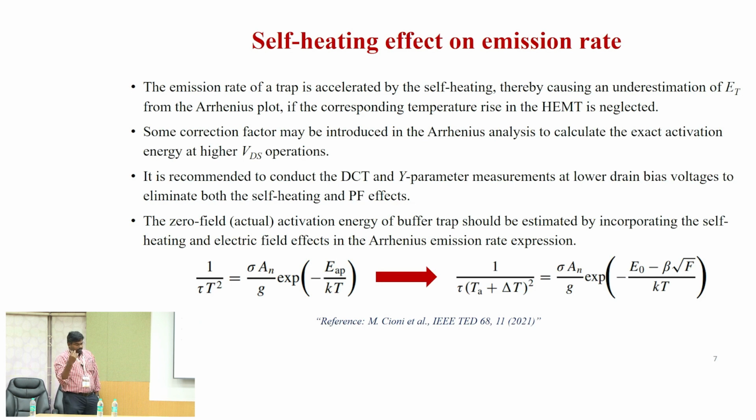Then the self-heating effect. In a normal case, we are doing wafer-level measurement. We keep the sample at the probe station or something like that, so we are always measuring the sample chuck temperature. But actually, because of the self-heating effect, your channel temperature may be higher than that. You are assuming that your base temperature is 300 K, but because of self-heating, your channel temperature may be more than 350 or 400 Kelvin.